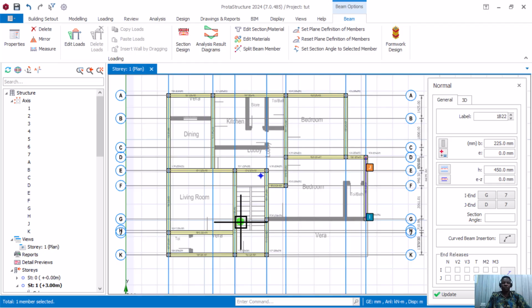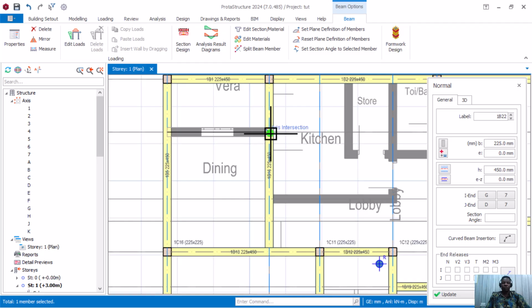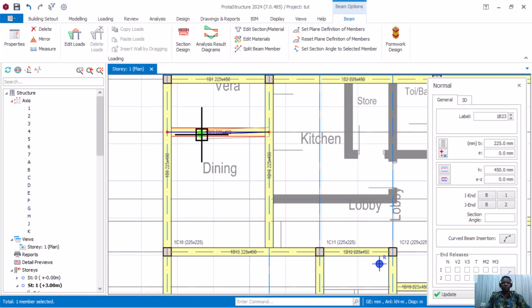Okay, so that's by the way. So we're going to insert another beam here. We have a beam over this area, so we're going to insert a beam here. So there's another beam. That's why we introduce this grid. Don't forget, when you're doing your GA, for every area where you need to introduce your beam, you are going to have your grid line there.